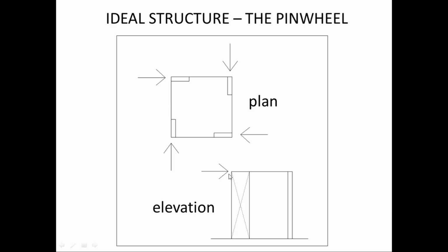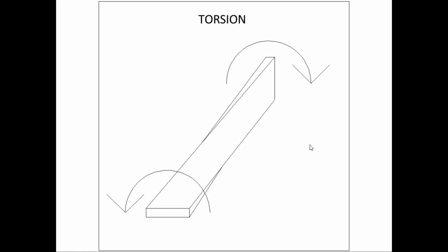So again, you can see that if I'm pushing here on this corner of the building, that is that triangle there. In fact, it's a flat plane now, so it's a continuous column, but there is again an invisible triangle here that pushes down into that corner and prevents the building from moving in that direction. The same in the opposite direction. There's the triangle again, invisible. Now, if I alternate these, if I rotate these around the central point so that I have one rectangular column going in each direction, the pinwheel, I'm resisting every conceivable lateral load direction onto that building. I hope that's clear.